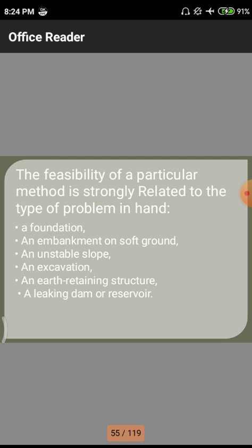In the total construction of a building, we first have to do some amount of groundwork. After the groundwork, we need to check the alignment of the land and use some material on the strata up to equilibrium conditions at a particular level. After that we do the foundation, then the plinth level, then columns. After that we go for shuttering work and slab, then partition walls, windows and doors, and next the brickwork.